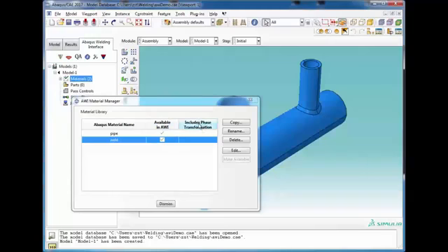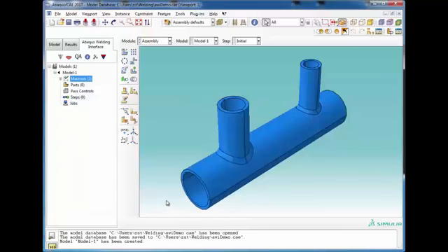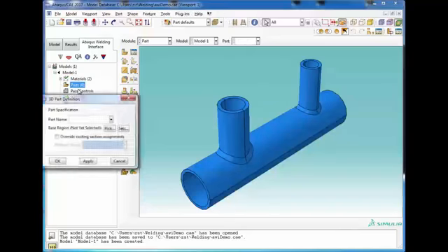Now this third column is whether these materials include phase transformation. Now there is a plugin that allows us to use phase transformations in our materials. It's a separate UMAT. So the AWI is linked to that plugin, but we're not going to use it in this case. So you see now that we've modified a couple of materials, now we at least have something that we could use inside the weld model. So we see this green check indicating that we can move to the next step.